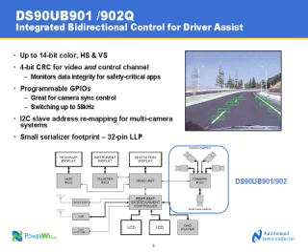The 4-bit CRC is an error detection for both the video and the control channels. We actually monitor the data and flag to the user if there's been any corruption of data for some reason, in both directions, the video being sent from the camera to the processor or any control information. And as Alex mentioned, these processors are often making very critical safety decisions based on the data they're receiving. So it's important to have this error checking to flag to the system if anything has gone wrong so that they can make adjustments in the type of safety decisions being made.